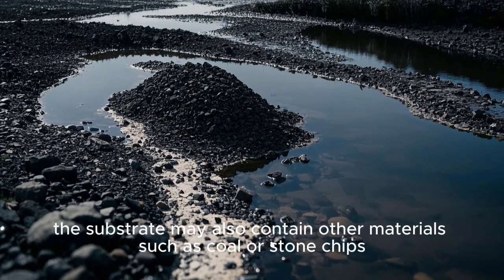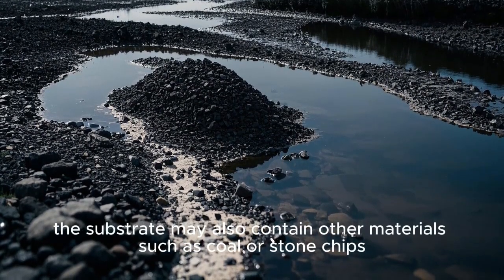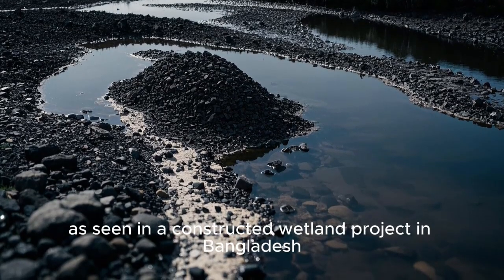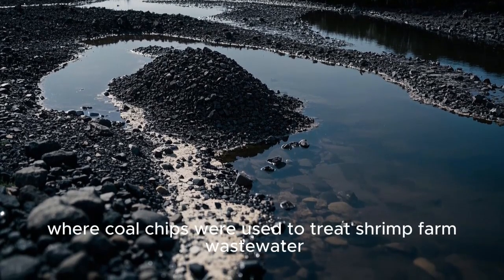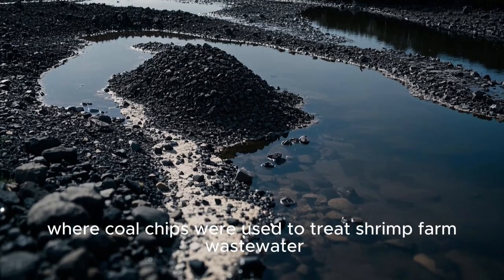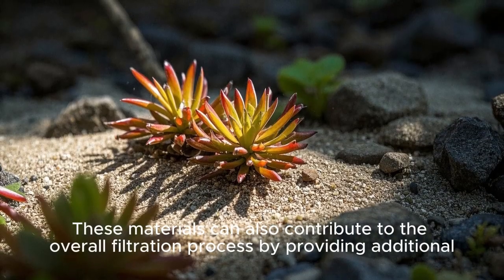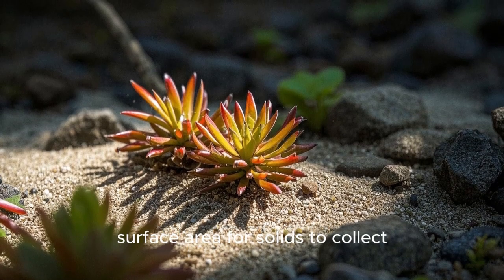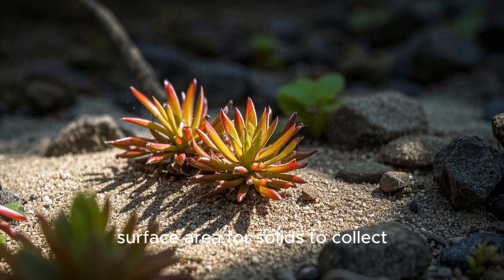In some cases, the substrate may also contain other materials such as coal or stone chips, as seen in a constructed wetland project in Bangladesh, where coal chips were used to treat shrimp farm wastewater. These materials can also contribute to the overall filtration process by providing additional surface area for solids to collect.